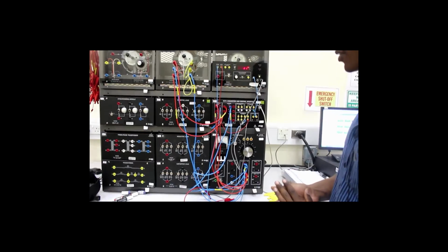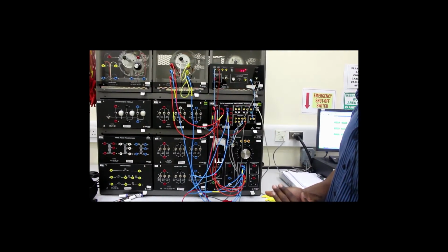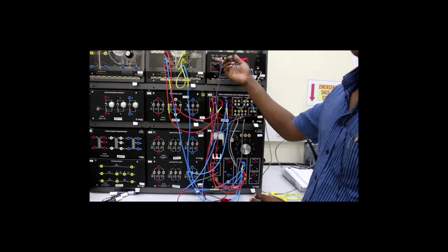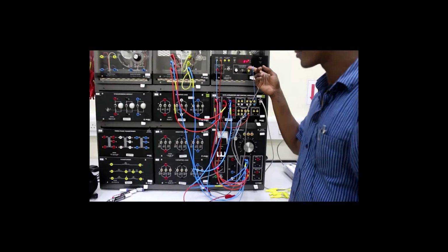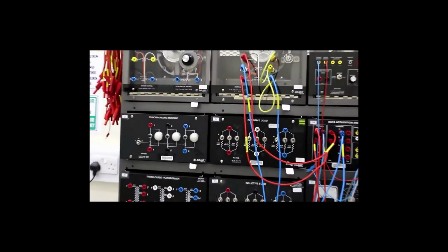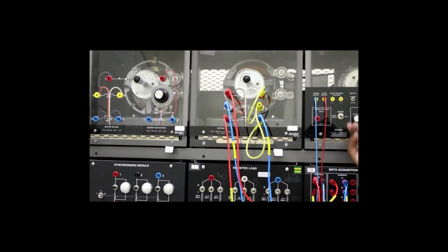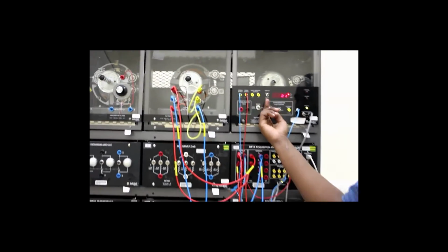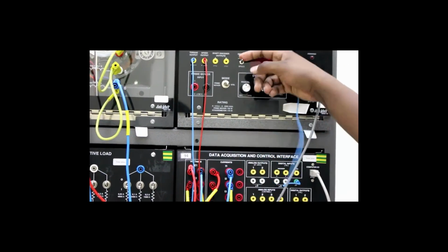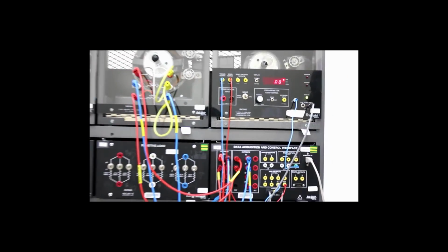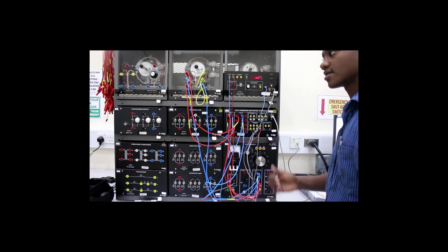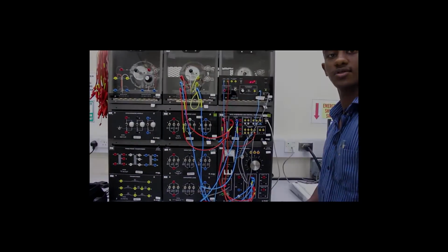Let's see now what we are going to see in the results. And don't forget the prime mover. Don't forget to couple the prime mover and connect the speed and output torques, and most importantly, don't forget to connect the ground from the data acquisition unit to the dynamometer. Make sure the dynamometer is on dynamometer mode, not on prime mover mode, and that the mode here is manual, and you can choose to measure speed or voltage as we said in the previous experiments. Set the control knob fully counterclockwise, and let's see what we are required to do in the experiment.